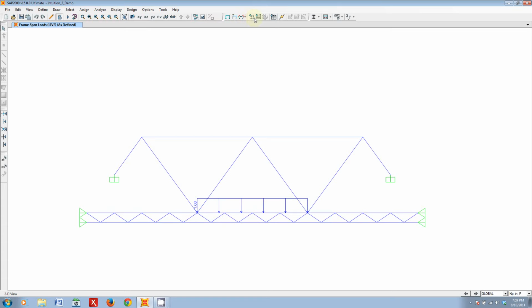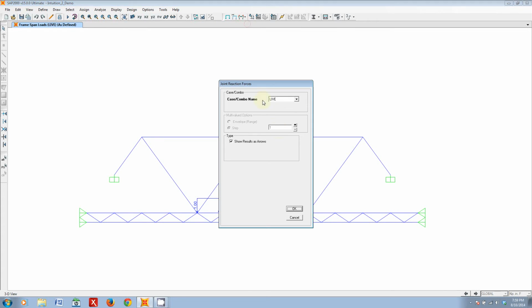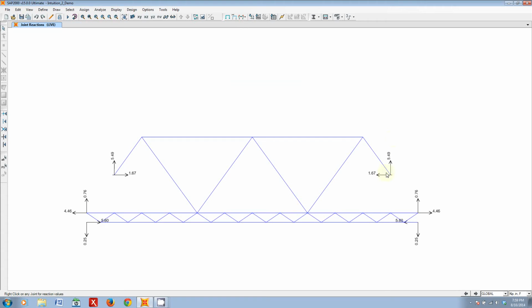So now let's visualize, I guess, our joint loads to see where our actual load is being carried. And check it out. So at these supports connecting to the overtruss, we have maybe something like 11 kips of the overall load getting transferred here, but look at this load is going down, so really this collection of supports is only carrying half a kip here, so it's only about a kip that's going to the supports of the girders, and the other 11 kips, pretty much the majority of the load, is going through the overtruss.